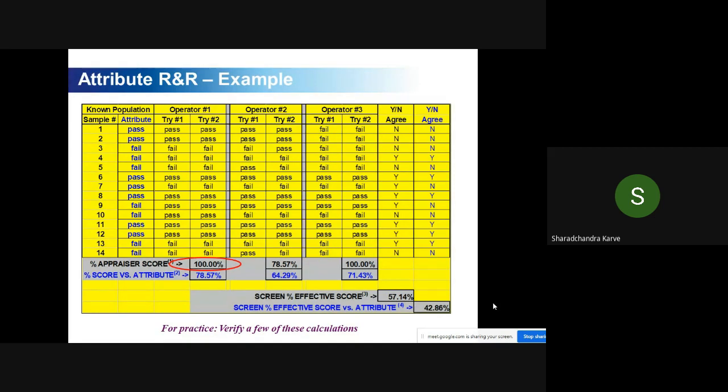So now, suppose with this type of measurement system and this type of operators present in the system, I try to improve the quality of the process. Will that really improve the process? No, because there is a variation in my measurement system. So what I need to do is set right my measurement system variation first, and then go for an actual improvement in the quality. Because even if I do some improvements in my process, that may not reflect in my quality, because there is a measurement system variation. That is what I mean by variation in the process. So go to the next slide, please.